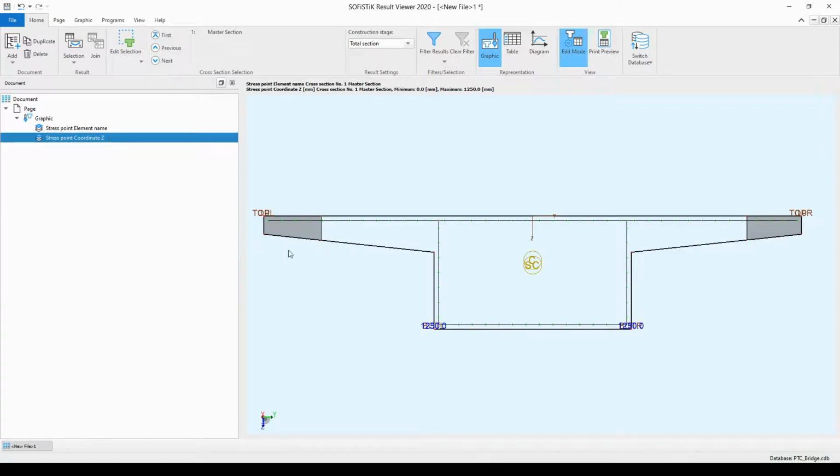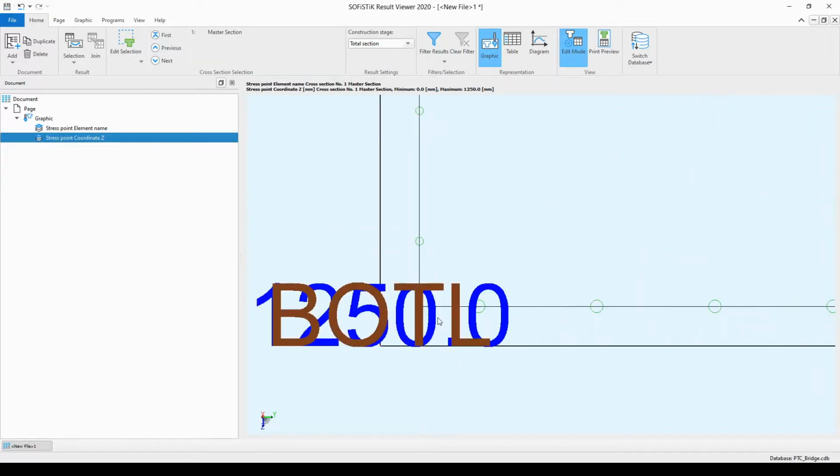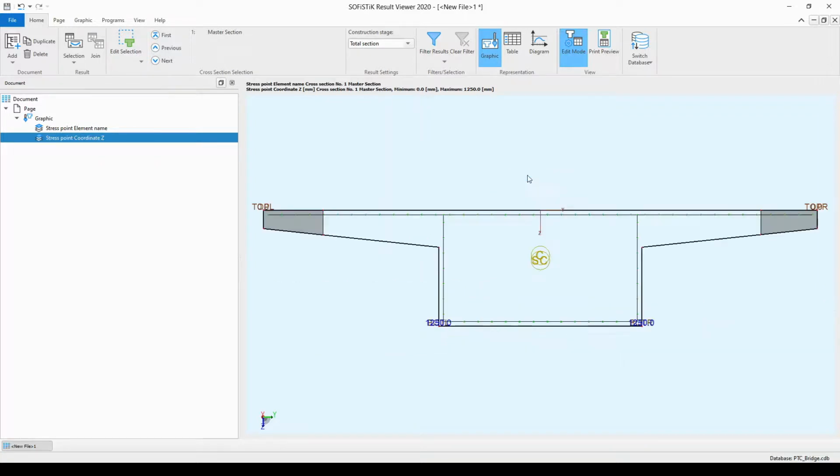Of course, they are presented on top of each other, that's why it is very difficult to see a clearer view. But if you zoom in by using your middle mouse button, you will see that really there are two things represented at the same location. If you now click with your right mouse button and choose the zoom border option, the cross-section will be presented again with its full extent. Now I'm going back and select the second layer and simply delete it with the delete button.